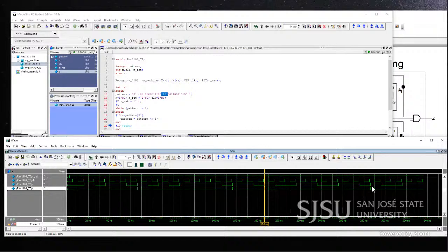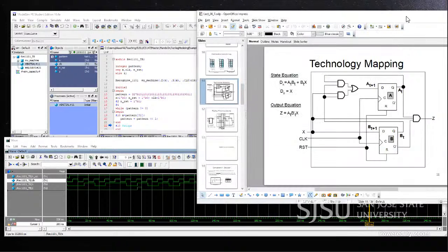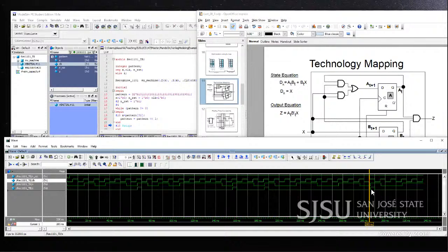And then towards the end, we have another 1101: 1, 1, 0, sorry, 1, 1 here, 1, and 0, and 1. So there it goes and goes high, recognizing the X. So it seems like this circuit is okay to recognize the incoming bit pattern in a sequential way.